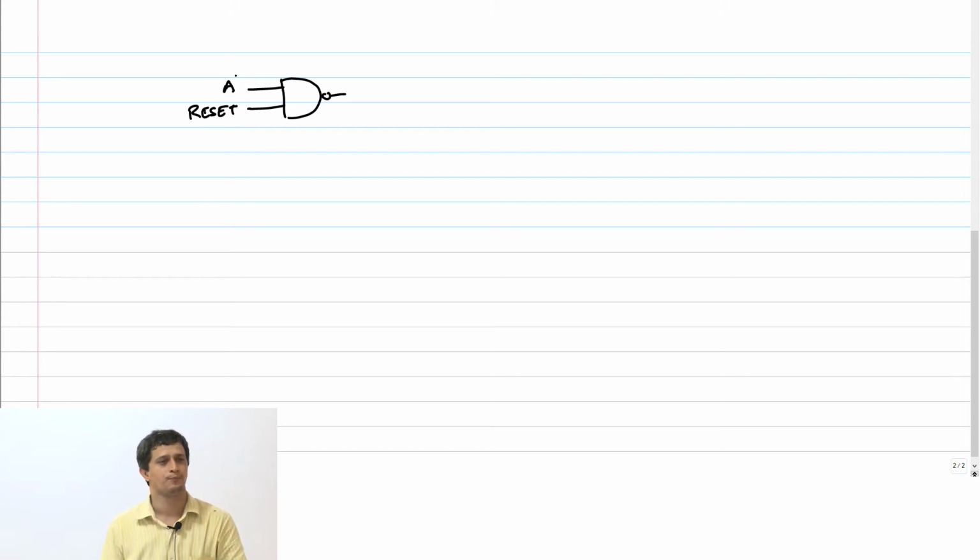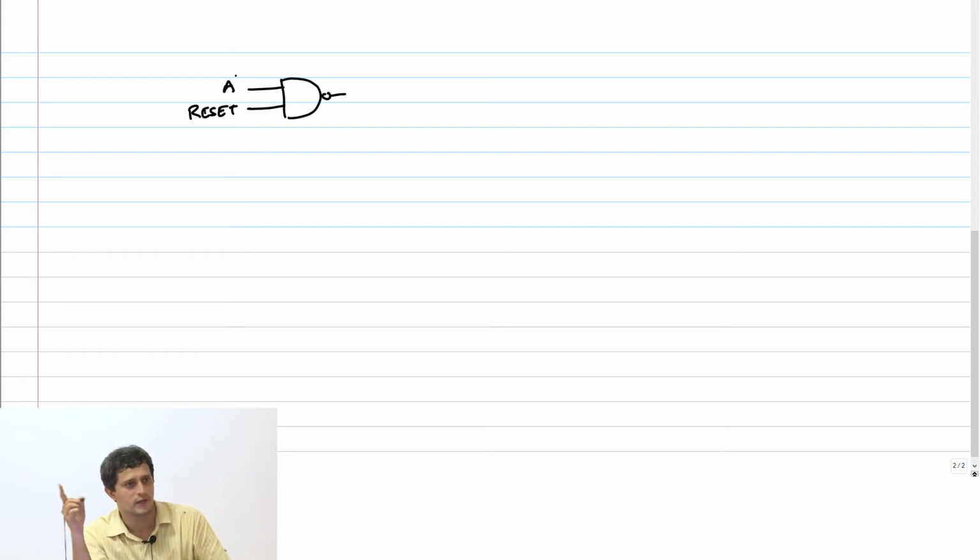Suppose I have a NAND gate, let's say with a signal like this, reset and an input A. Now this reset is very not timing critical, right? So therefore you connect that guy to the bottom transistor. The signal A is basically the critical signal which is going to control the stuff inside your circuit, right? So that has to switch as fast as possible, right?